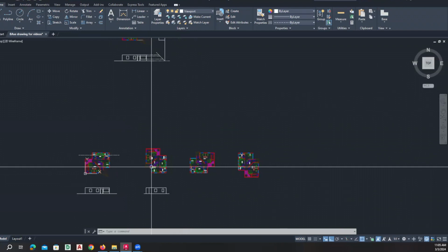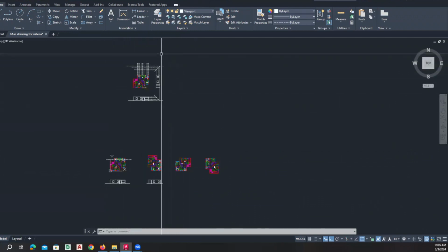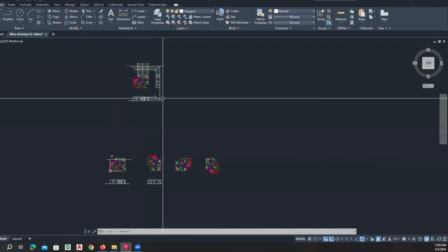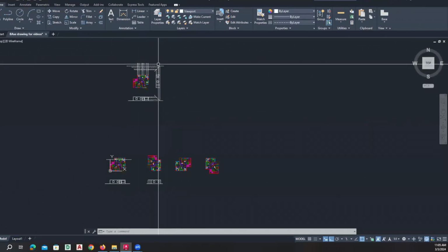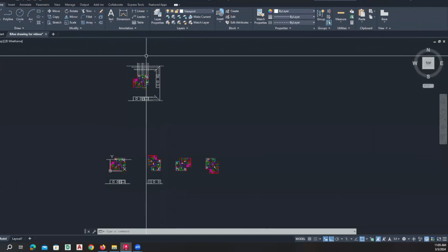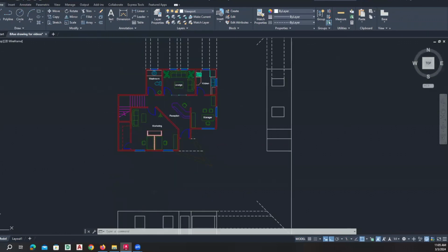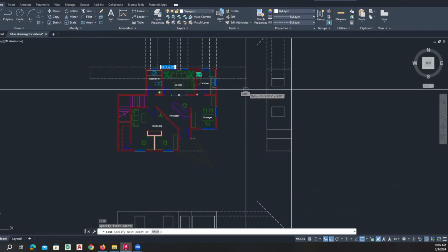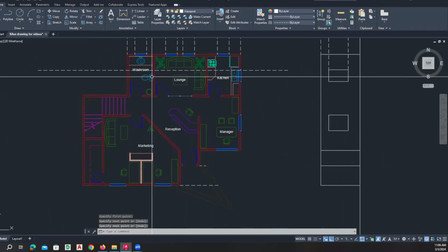Okay, so that's how I would like you to proceed with your elevations. Try to change your UCSs around so that they're parallel to the sides that you're drawing, and then you will draw the elevations around them. Now, again, like I said before, if I were to draw a section elevation, which is what you're doing for your assignment, right? You're essentially having this drawing,